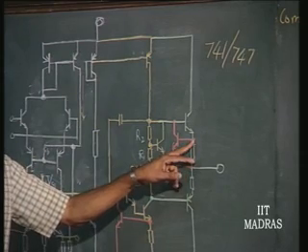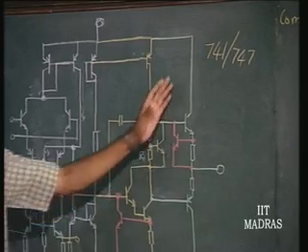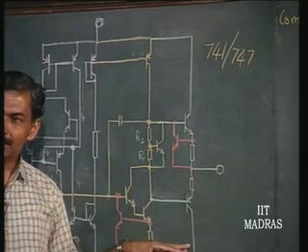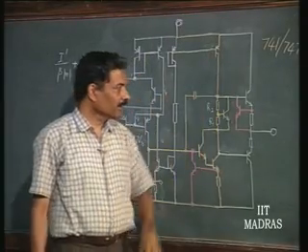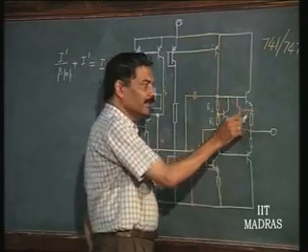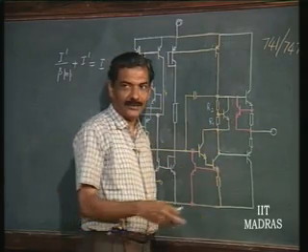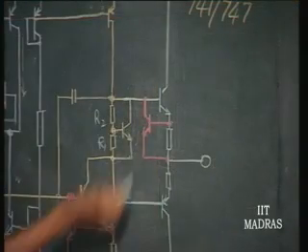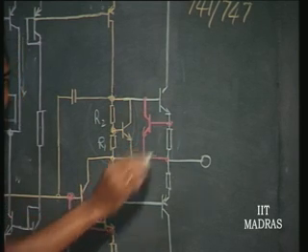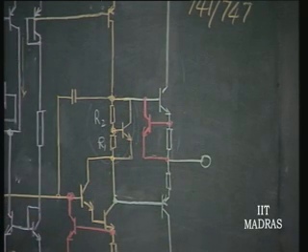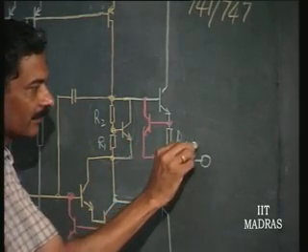These resistors are current sense resistors for protecting the output stage. Output stage, as we see, is nothing but again PNP NPN combination, okay, and you can see the straightforward protection which is necessary for any output stage that we had learnt in voltage regulator being still used here. This transistor normally is off, primarily because this voltage is not good enough to bias it in the forward direction. So, this is the sense resistance or sense.